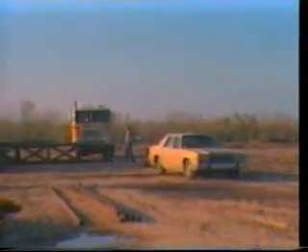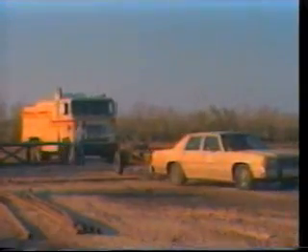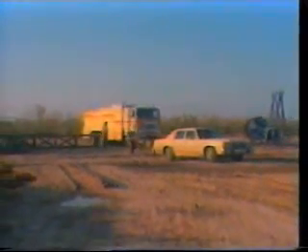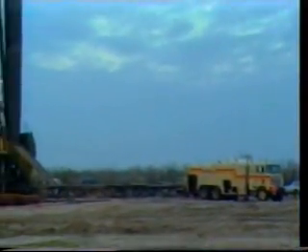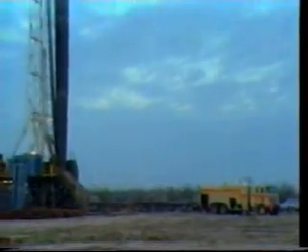It is the logging crew's responsibility to find the drill site and be at the location at the specified time. Under certain conditions, special equipment may be situated at the well site to ensure that the logging unit can be brought onto the lease. The preferred location for setup and logging is for the logging unit to be in a backed position, beyond the pipe rack, and accessible to the end of the catwalk, with an unobstructed view of the rig floor.